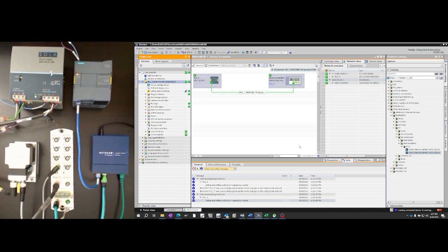Okay, you know you're online with the PLC when you have all green circles on the left-hand side under the project tree. And you can see here my program blocks, my standard program blocks, the safety administration, and all of my distributed and local I/O is all green. So this means I've performed my networking correctly and I've added the correct modules and it's detecting the correct devices.